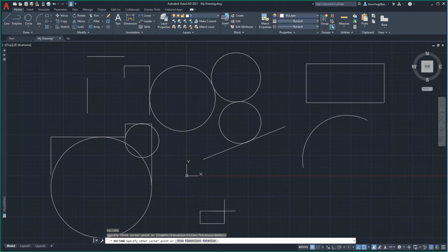And since we have chosen the first corner, we will assume this to be the lower left-hand corner of our rectangle. We want to type in the command line the @ symbol by typing Shift 2. In English language terms, allow the @ symbol to mean from where I started, go. This is a way to instruct the software to go or connect to a point relative to the chosen starting point.